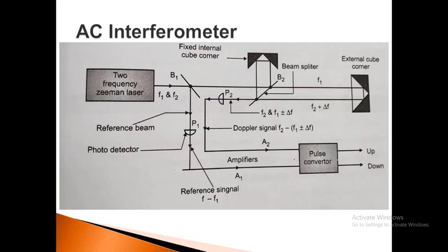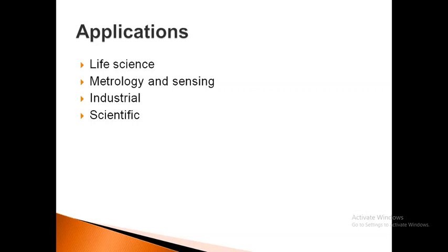Next, the applications of laser interferometers. Laser interferometers are used in interference measurement where higher accuracy is required, and are used for checking the movement of machine tool tables. They are also used for aligning and checking large assemblies, and can be used for intricate machine part measurements.